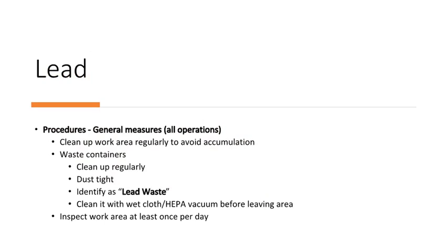Waste containers must be used. Regular cleanup must be dust tight. The container must be identified as lead waste and must be cleaned with a wet cloth or HEPA vacuum before leaving the work area. The procedure must include that the worker must be inspected once per day.